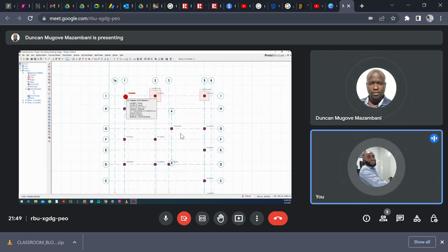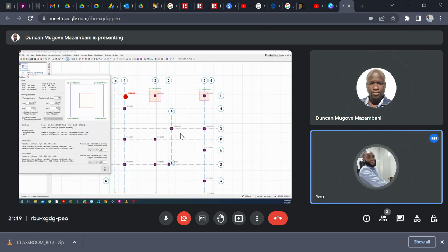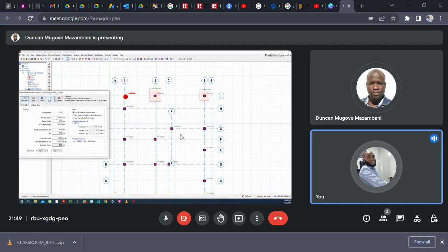Now let's try that one. That one I'm thinking it will be a combined footing because of how close those columns are. So let us try that. If it is not a combined footing, then we can move on. So insert part base, calculate, square it first. Okay, then okay, that's fine. Yeah, it's a 1 meter footing. Say okay. Then inside the one say okay.